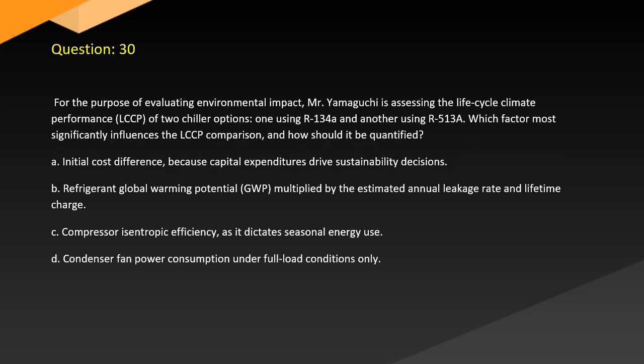Question 30. For the purpose of evaluating environmental impact, Mr. Yamaguchi is assessing the life cycle climate performance (LCCP) of two chiller options, one using R-134a and another using R-513A. Which factor most significantly influences the LCCP comparison, and how should it be quantified? A. Initial cost difference, because capital expenditures drive sustainability decisions. B. Refrigerant global warming potential, to be multiplied by the estimated annual leakage rate and lifetime charge. C. Compressor isentropic efficiency, as it dictates seasonal energy use. D. Condenser fan power consumption under full load conditions only.